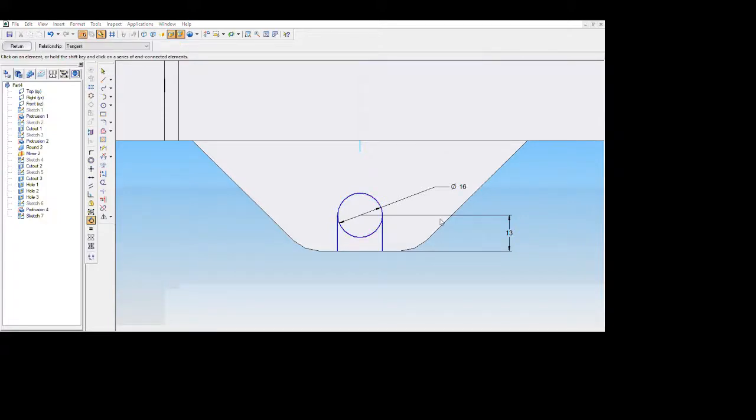As you can see, it is showing the requested change conflicts with the existing relations, that is, it's already tangent. Again, check for this line also. Connect this, or else before connecting, trim this excess part. Now join this line.